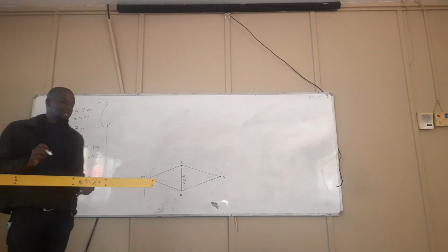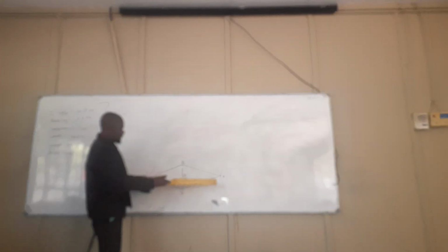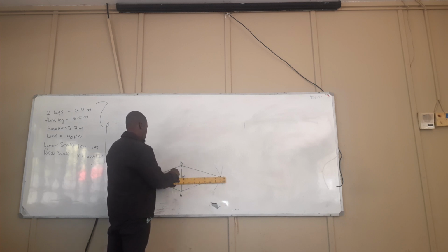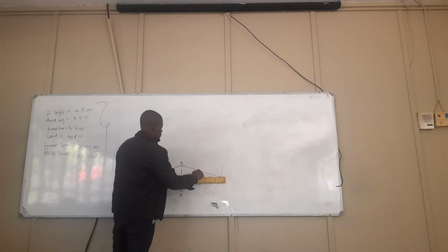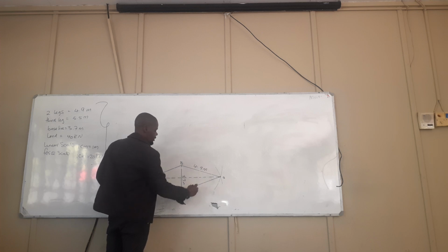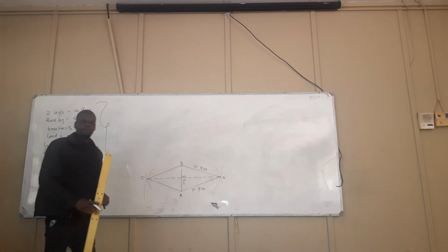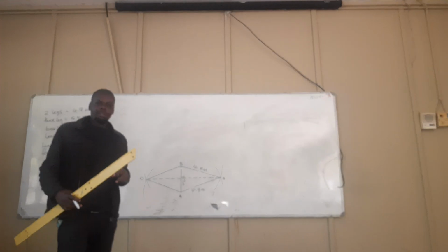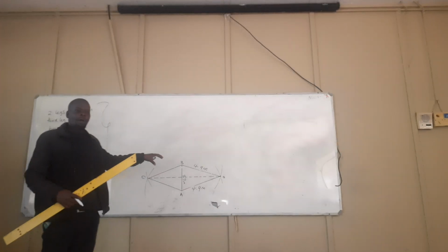After that, just join those 2 points, O to C, you can just use a dashed line, or a broken line. Right, so we say this is the true length of two of those legs that are equal, measuring 4.9 meters. So whatever that we've projected here is the floor plan of the tripod, right? This is the floor plan of the tripod.